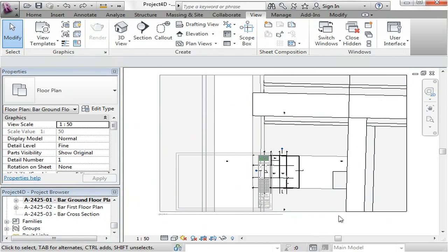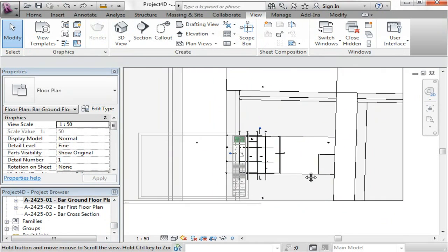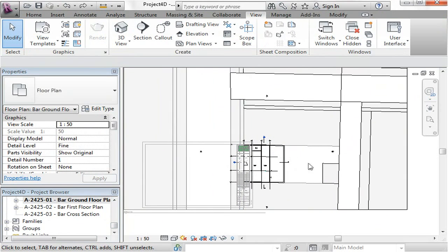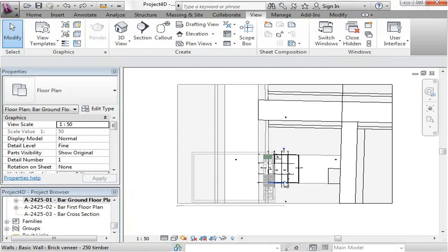And by activating the view, it allows you to stay within this sheet file, but hop into that view so you can make modifications. As I move my mouse around, the elements inside that view highlight, which indicates that I can actually continue modeling within that view if I like. So I'm in the active view itself, if that makes sense.